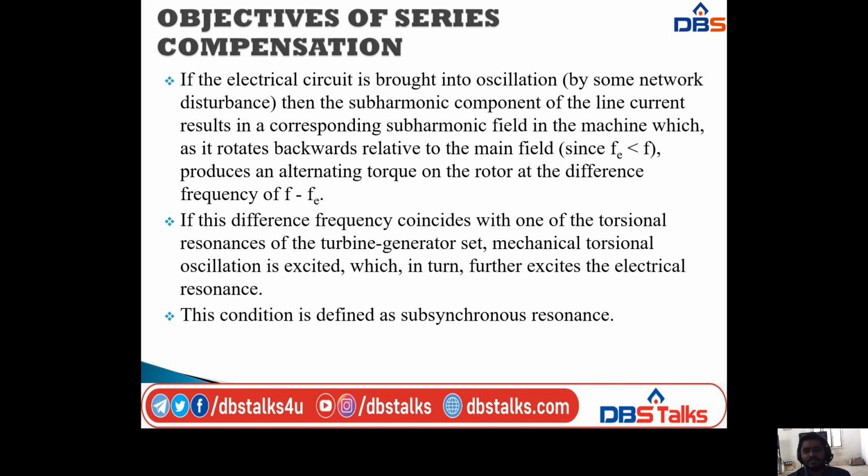If the electrical circuit is brought into oscillation by some network disturbance, then the subharmonic component of the line current results in a corresponding subharmonic field in the machine, which, as it rotates backwards relative to the main field since Fe is less than F, produces an alternating torque on the rotor at the difference of frequency, that is F minus Fe.